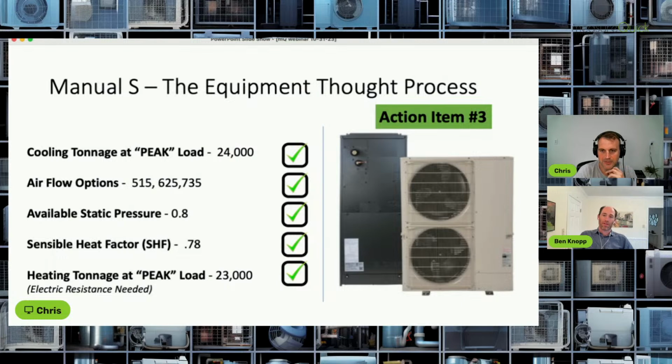There's a little bit more to it than that, but something to look at when you're looking at variable speed equipment and sizing to a cooling load, especially in a mixed humid climate like Virginia, or a humid climate, anywhere where it's critical that you control moisture. Look at the minimum capacity. So what's its turn down ratio? What's the minimum?